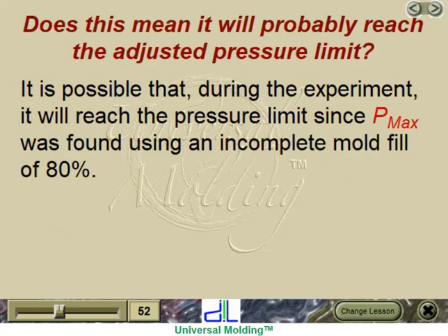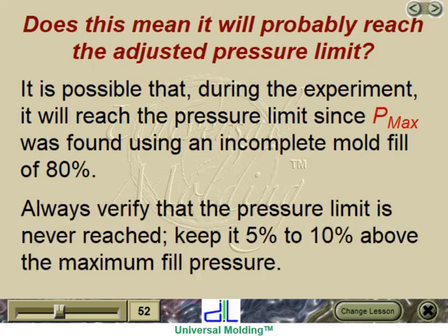It is possible that, during the experiment, it will reach the pressure limit, since Pmax was found using an incomplete mold fill of 80%. Always verify that the pressure limit is never reached. Keep it 5 to 10% above the maximum fill pressure.